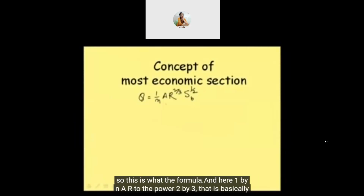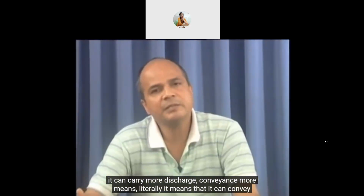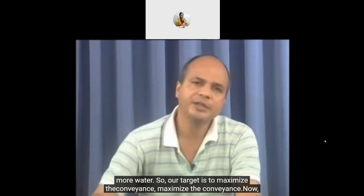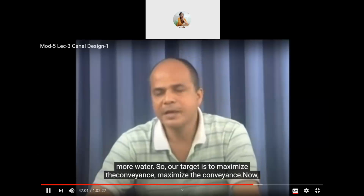So this is the formula. And here 1 by n A R to the power 2 by 3 is basically the conveyance K. And when our conveyance is more, that means it can carry more discharge. Conveyance more means, literally, that it can convey more water. So our target is to maximize the conveyance.